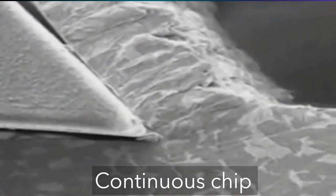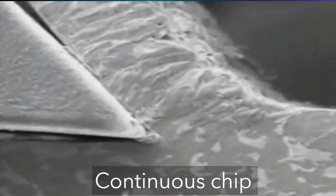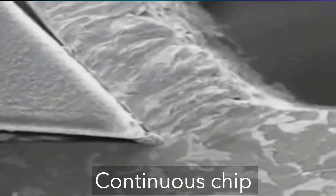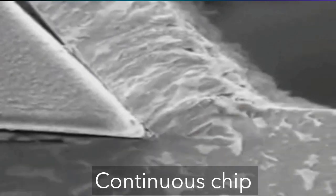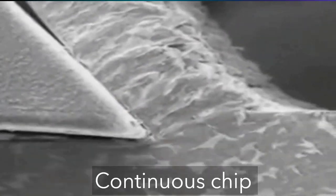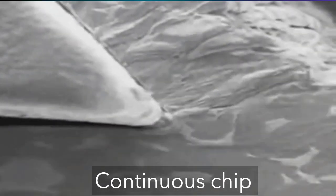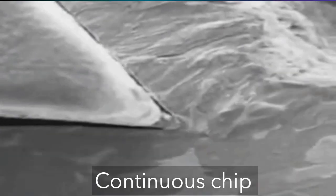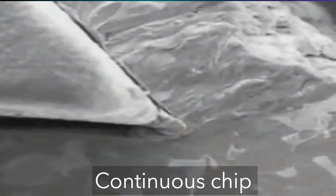When ductile work materials are cut at high speed and relatively small feeds and depths, long continuous chips are formed. A good surface finish typically results when this chip type is formed. A sharp cutting edge on the tool and low tool-chip friction encourage the formation of continuous chips.